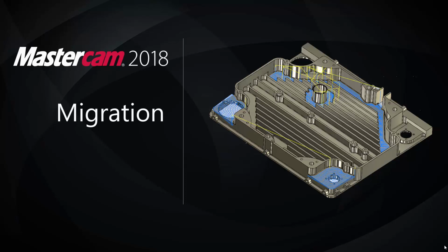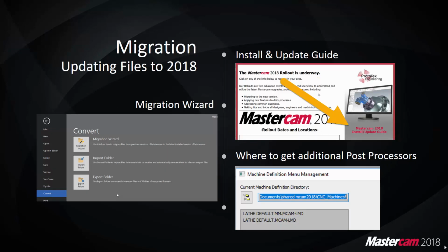An important step in getting Mastercam 2018 up and running is migrating all of your critical Mastercam files to 2018. Things like machine definitions, control definitions, post-processors, tool libraries, operation defaults, and more. To start, we'll take a look at the install and update guide we've created. What is it and where do you get it? I'll run through the migration process and we'll have a brief discussion on post-processors.